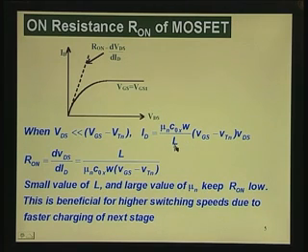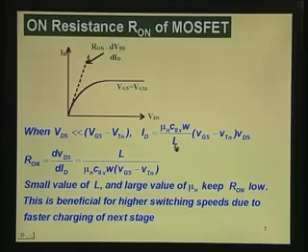Notice everywhere, these two terms, the channel length and the mobility, will haunt the speed of the device. It is the one which troubles the speed of the device, because that is the one which controls the cutoff frequency of the device through this on resistance. So, this is the well known equation.